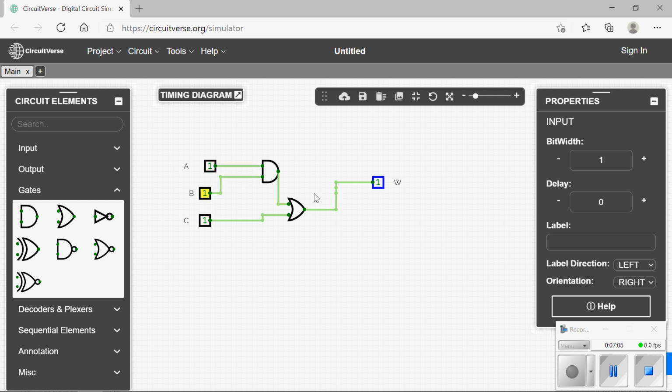There may be times where you exclusively want A and B to turn it on, or C, but not both. This could perhaps be two different things making a request, and the request can only be served by one or the other at a time. And in such a case, you would use this. This is similar to an OR gate, except this exclusive OR gate will not come on if they're both on, but you'll learn about those later.